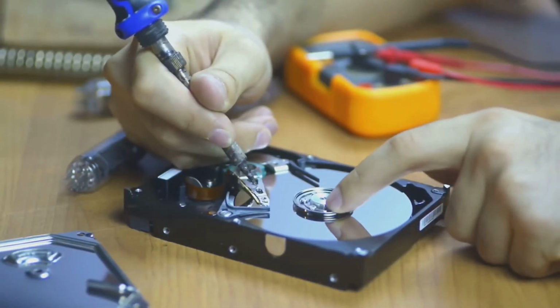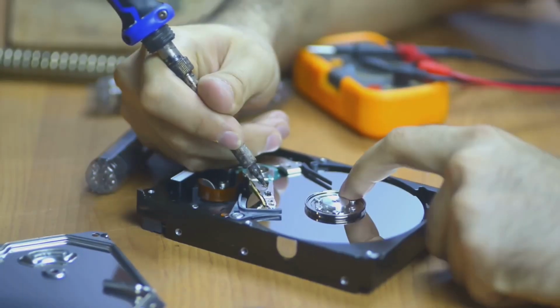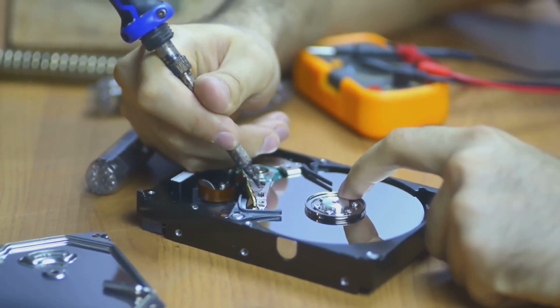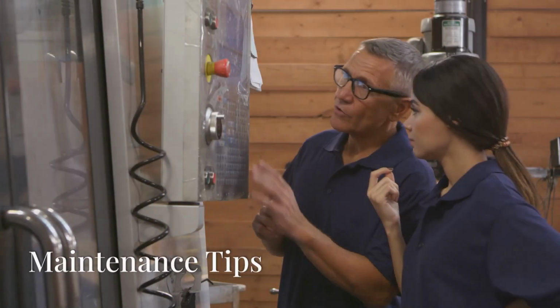Clean or replace. If you suspect mechanical wear, try cleaning the encoder disc and sensor. If that doesn't work, you might need to replace the encoder. Remember, safety first. Always disconnect the power before working on any electrical components.